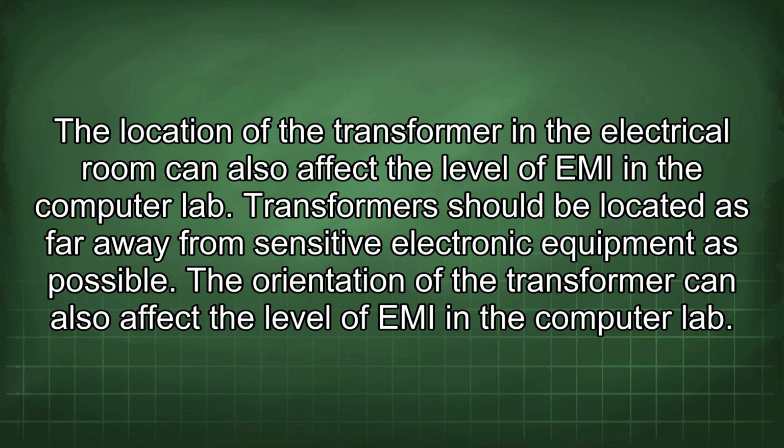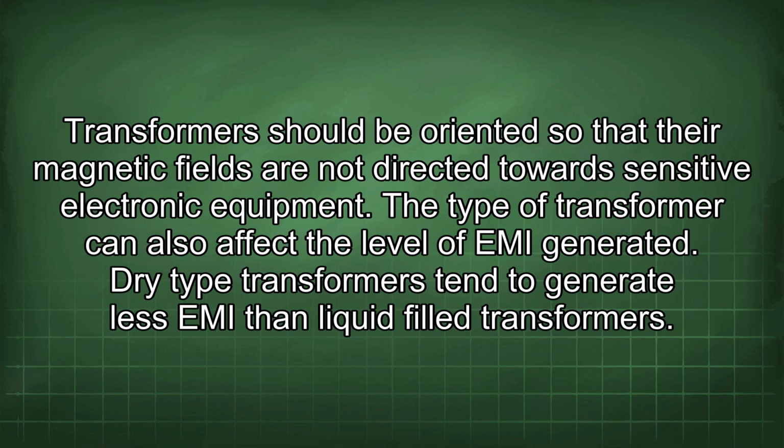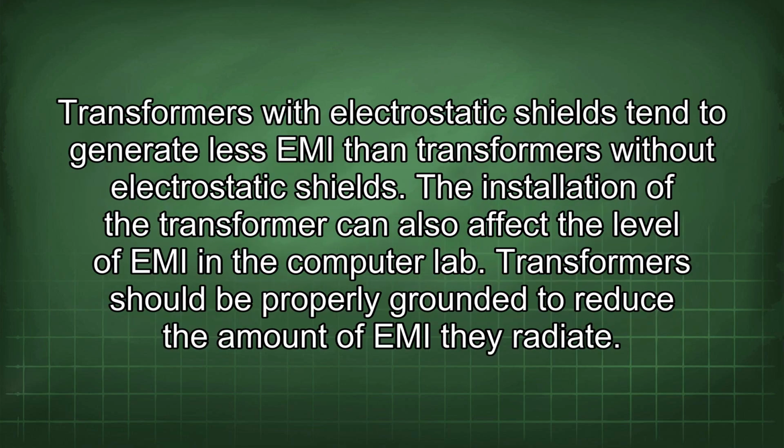The orientation of the transformer can also affect the level of EMI in the computer lab. Transformers should be oriented so that their magnetic fields are not directed towards sensitive electronic equipment. The type of transformer can also affect the level of EMI generated. Dry-type transformers tend to generate less EMI than liquid-filled transformers. Transformers with electrostatic shields tend to generate less EMI than transformers without electrostatic shields.